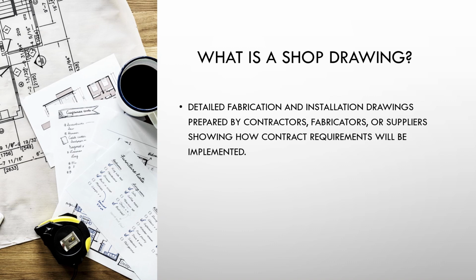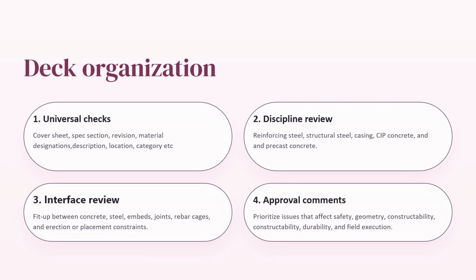Shop drawing plays a critical role in ensuring that final construction matches the original design intent and adheres to all specified requirements. Shop drawings are subjected to a review and approval process by architects, engineers, and other relevant professionals involved in the project. This review process is done to confirm that the proposed drawing details comply with the overall project specifications. There are various important factors while checking shop drawing.